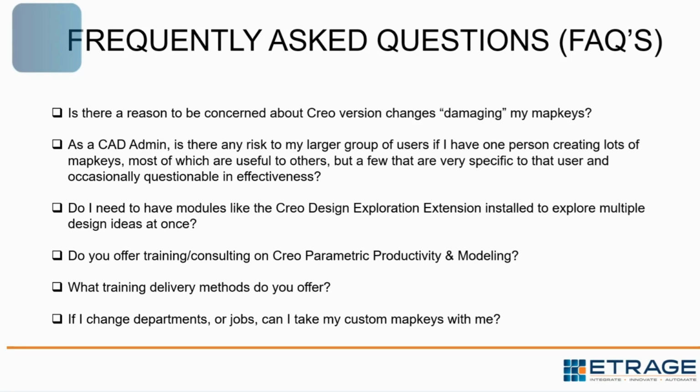Now, in addition to that, you can also have user-specific configs. A particular user could have their own set of additional configs that they create as they work, to customize the look and feel of how they work, right? And those can be saved into another config file as well. When Creo launches upon startup, Creo grabs all the admin configs plus any user-specific configs all together and uses them to run the Creo session.